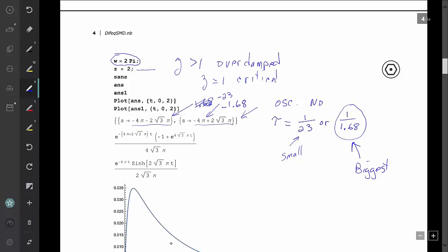The idea is what the time constant is supposed to tell you is the length of time it's going to take until it gets about 62 some odd percent of where it's headed. And it hasn't arrived until every part of it arrives. So this one will get there quickly. This one will get there fast. The big one here is the one that's going to last. So to be fair, you give this as the time constant. Give the biggest one. Okay, so that's how you handle multiple values.